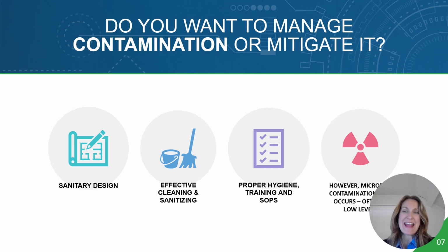So how do we mitigate having biofilms, cracks, or other deformities in our process? Number one, you want to make sure that you're proactive in having a good sanitary or hygienic design in your process. That comes down to your equipment, your layout, and that you have everything properly polished in place. You have 3A or EHEDG certification. But that first step is really critical to make sure that you're not introducing risks just into the design.